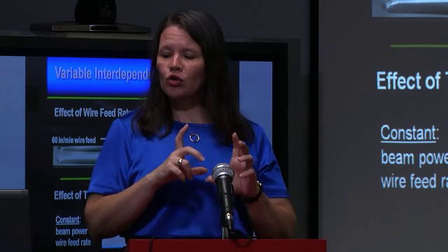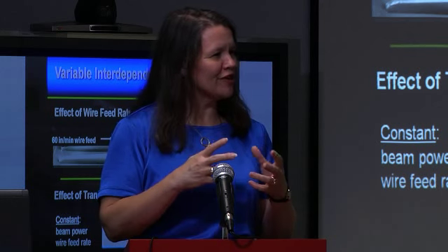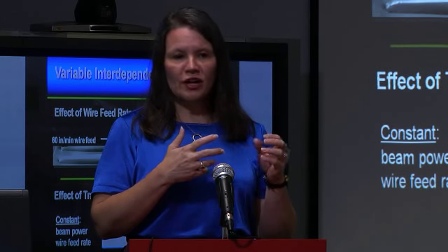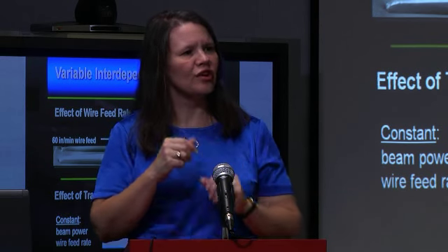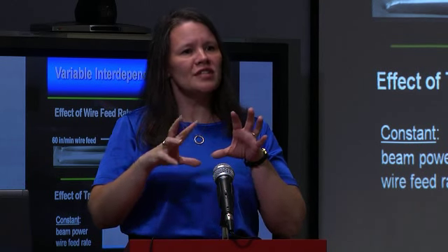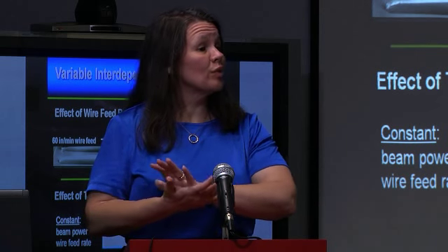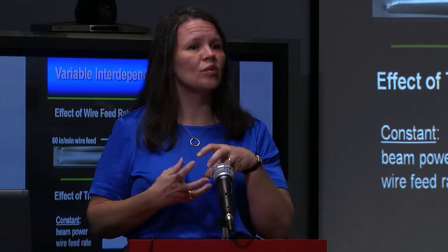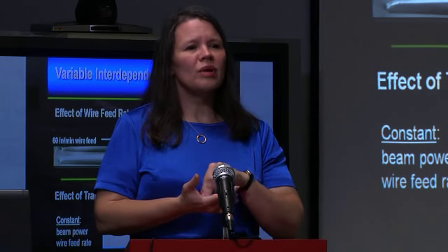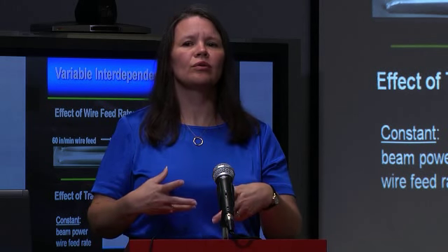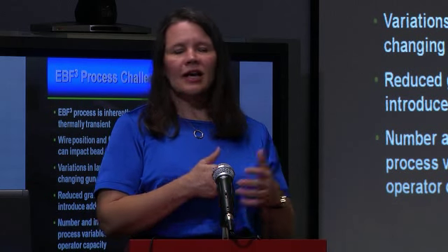If I slow down or speed up how fast I'm moving the table, I have a similar effect but different. As I speed up, I've got less material going in any one spot, so my build height is going to go down. Trying to understand all of these interdependencies and how they impact my end result are some of the things that we're wrestling with. And in order to make the process something that's really useful and get it out into industry, you've got to be able to understand enough of these, either through modeling or through experiment, so that you can control the process. And so really that's what this slide is trying to say.